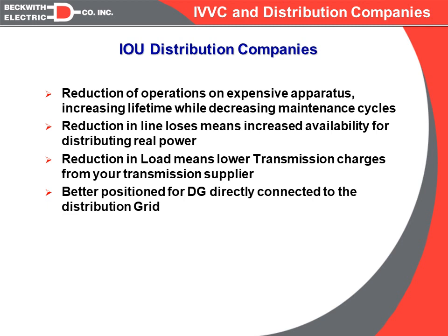Another thing we can talk about is DG. We know that distributed generation is going to be coming on board, and it is going to affect the voltages and the way you regulate the voltages on your system. And by having an integrated volt VAR control system in place, you'll have more flexibility on incorporating the DGs when they do come into play.